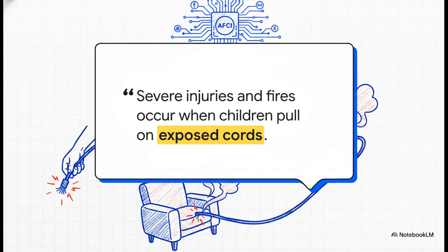Now, on the fire prevention side, the panel dug heavily into incident data regarding arc fault circuit interrupters. And this quote highlights exactly why expanding AFCI is absolutely critical. These aren't just arbitrary rules, guys. The metrics prove that localized structural fires frequently start from mechanical damage, like kids pulling on exposed appliance cords or cords getting crushed behind a heavy couch. AFCIs actively scan the electrical waveform for the erratic signatures of those arcs, shutting down the circuit before a fire even has a chance to ignite.